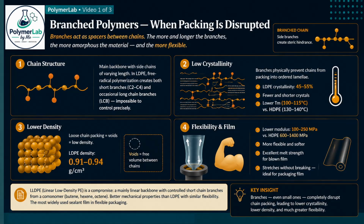Those branches stick out sideways from the main chain. When you try to pack two LDPE chains alongside each other, the branches get in the way. They create a steric hindrance, physical interference between neighboring chains. As a result, chains cannot approach each other closely enough to form well-organized crystal lamellae.